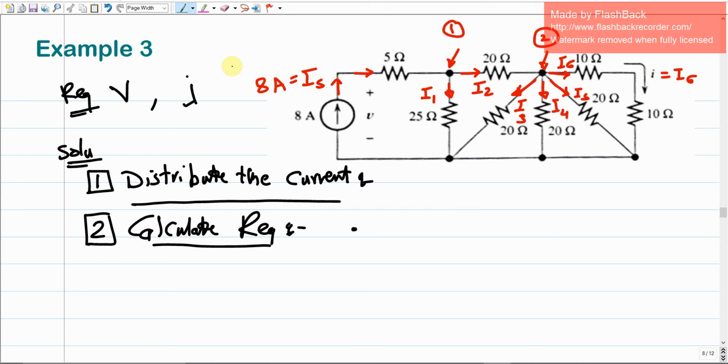First of all, we combine these 2 resistances, the 10 ohms with the 10 ohms, into one equivalent resistance, R equivalent 1, where these 2 are in series. Why series? They have the same current. So R equivalent 1 should be 20 ohms, the sum of 10 plus 10. Make sense?